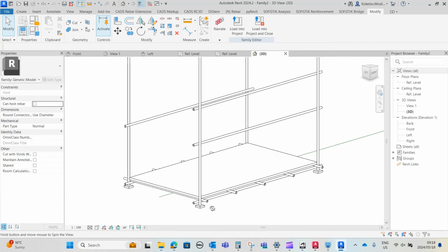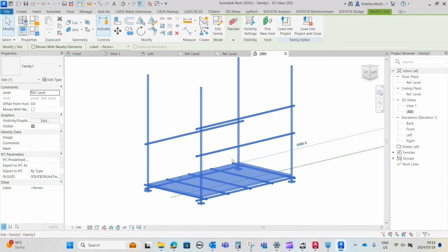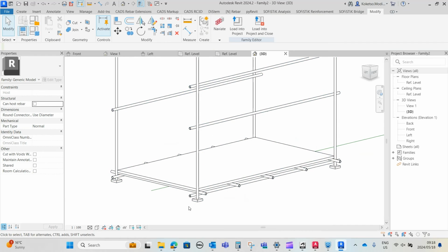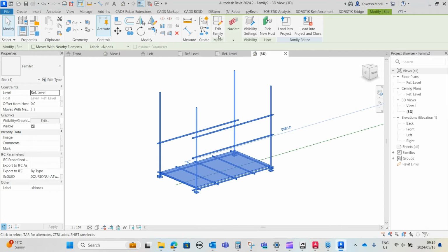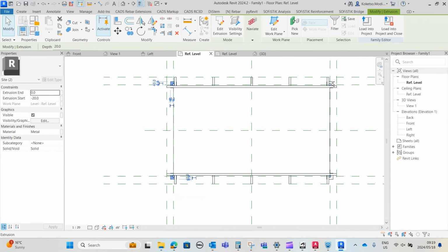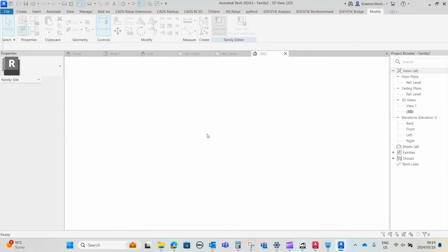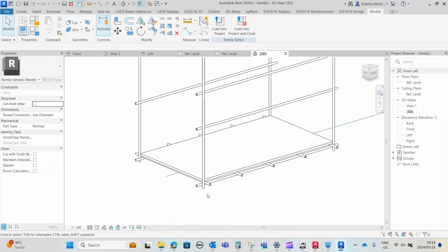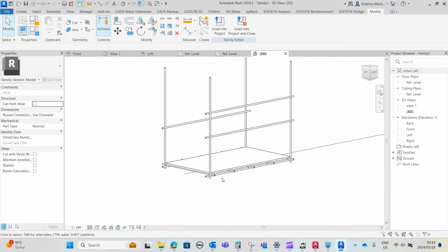So from the 3D view, it's gonna be tricky when we apply the lift parameters because we have these bases, and I don't want these bases to be placed on top like this. So I'm gonna open up my family again on the side, and then I'm just gonna remove these steel bases. And then I'm gonna load it into our project, override existing views. Now we don't have the bases. I'm gonna model these steel bases on the line-based family.